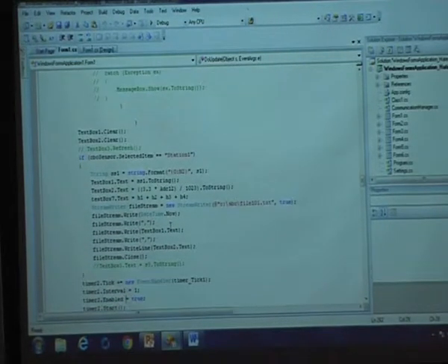So now the condition comes here. If the combo box selected item is equal to station 1, it means that when I am running my user interface, I will be selecting from which particular sensing station I am collecting the data. So if the selected station is station 1, whatever values you collect, put them in textbox1.text equal to the converted value. Similarly, textbox2 is connected to the corresponding analog to digital converted values.